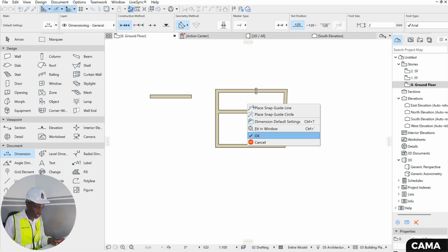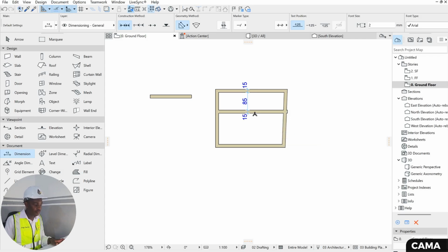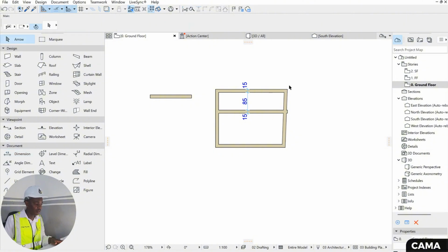85 centimeters. Why 85 centimeters? Because the wall thickness is 15 centimeters, meaning if you wish that your wall should be at exactly 100 centimeters spacing, you need to displace it at 115 centimeters, including the wall spacing. I think we are done with our first tool.